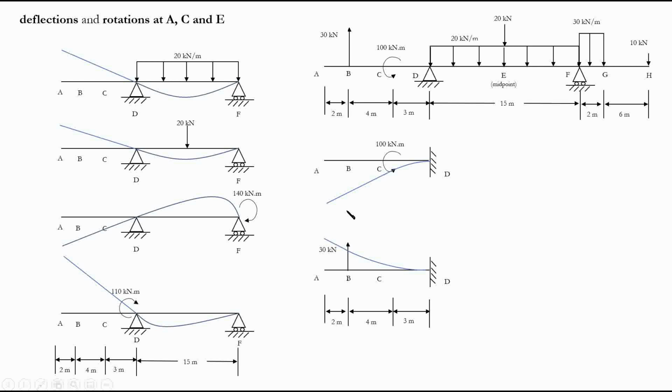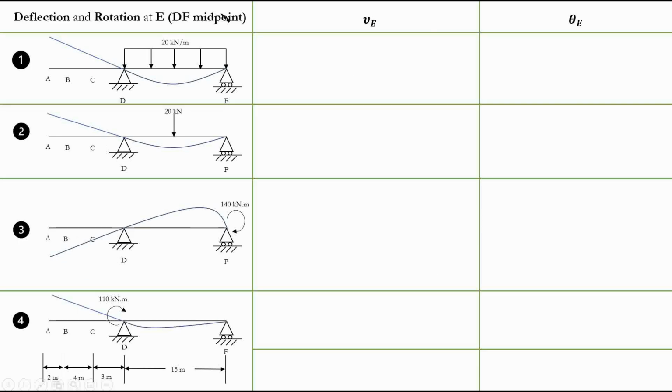You see, this linearity portion that we are discussing is going to be the main and most challenging part in finding the deflection values using the method of superposition. Otherwise, when you want to find deflections, it's clear: you can get the values from your tables and find it in the middle here and the middle here, as you'll see when we find it for point E. So these are very important to consider. Now we can just name these cases 1, 2, 3, 4, 5, 6 to make it easier for us, and then start with the deflection for point E.